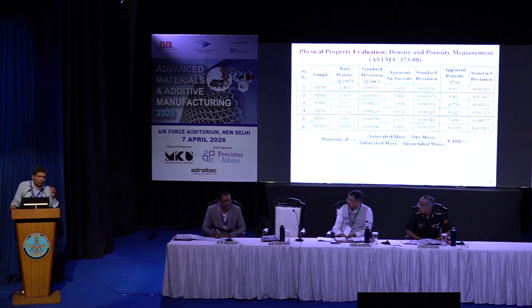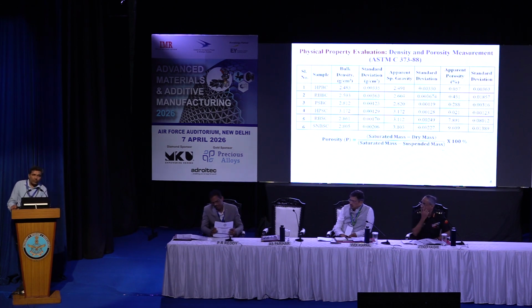of TiB2, and that increases the fracture toughness from 3.5 MPa root meter to approximately 4.5 MPa root meter. And also if we are increasing the thickness of the ceramic, the formation of the circumferential crack will be less, so the probability of stopping the close vicinity shot in the inter-shot distance of 51 millimeter will be good enough. So now with the R&D done, the type of ingredients and the understanding of the circumferential crack, we have both solutions, and even the tile solution and the monolithic plate solution are able to stop the 51 millimeter inter-shot distance of both level 5 and level 6 of the BIS.